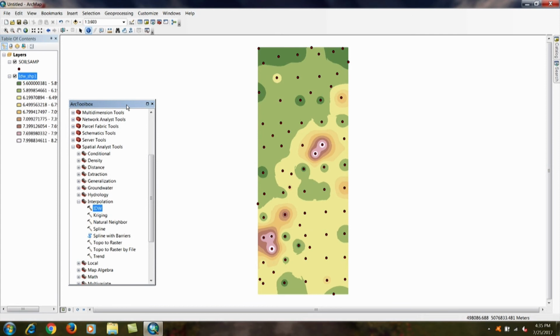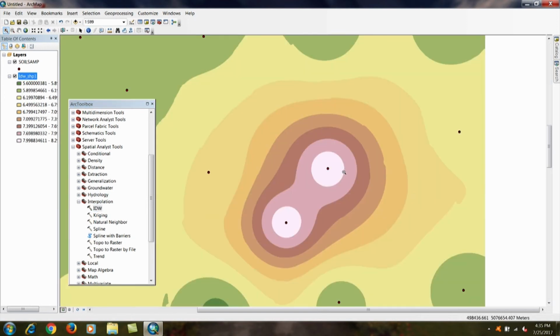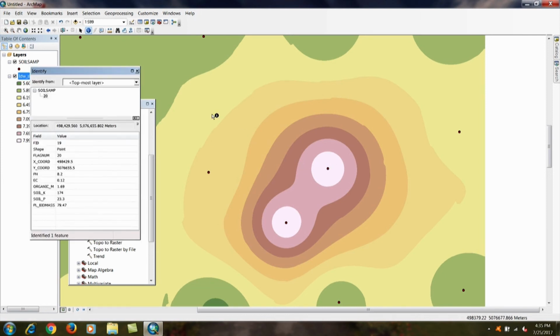Now, how good is the interpolation by this IDW, especially with this data set? This can also be checked. If I want to search what happened to these input points against the new values created through the generation of the digital elevation model, I can search all layers together.